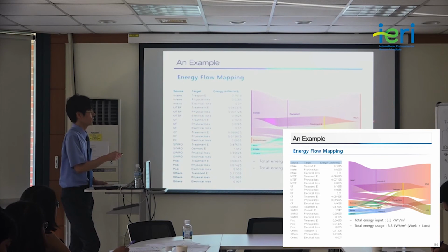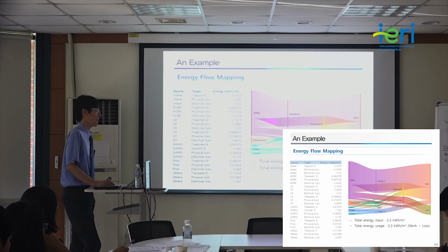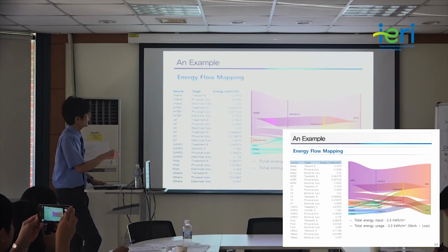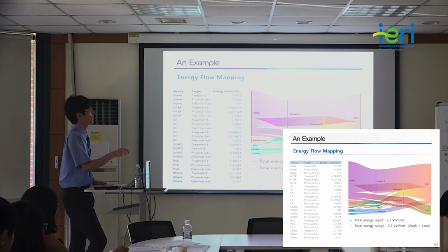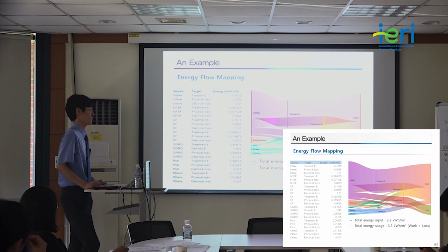And some of the energy was used to overcome the osmotic pressure. Some of the energy was used to separate water from salt. But some of the energy was wasted due to this irreversible energy loss, due to some friction losses, due to the losses by fouling or other problems. So if you supply this amount of energy, in the end you will have the energy used for working and energy wasted by this loss, and that ratio is actually the plant energy efficiency.